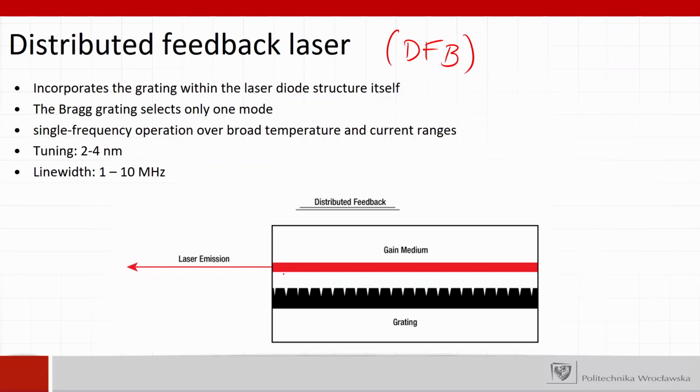The main principle of this resonator is that there are no mirrors, basically, but the mirror is formed by the difference between the refractive indices of the materials that are used here, because the semiconductor will have a high index, let's say at the level of maybe even 4, and the index of air is at the level of 1, right? So the reflectivity of such a border between the semiconductor and atmospheric air will be at the level of maybe even 40% roughly.